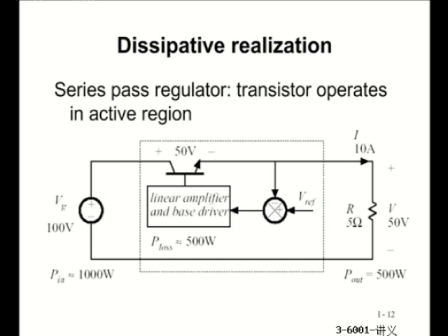Okay, if you have made some hardware electronic circuit before, very often the power supply for that electronic circuit is actually formed through a three-terminal series regulator, like 7805. This is a chip supplying 5 volts positive voltage. 7812, that's 12 volts, something like that. Those are based on this.